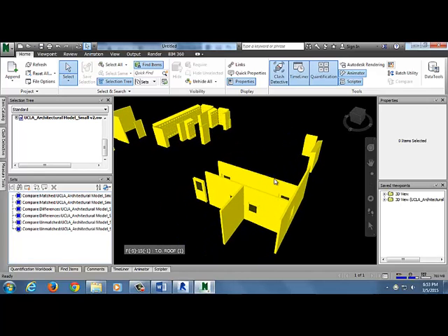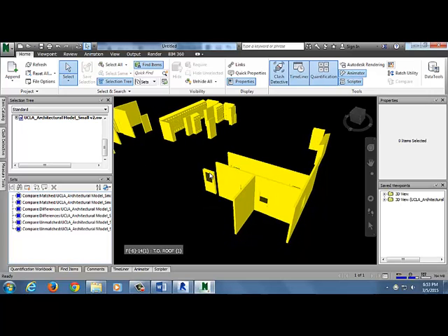Now just because it's in yellow and it's deleted here doesn't mean there's no wall there anymore, right? Sometimes they could have deleted a wall and then added one back in the exact same place with just a slightly different name. So you have to be careful about that. Just because it's yellow or cayenne doesn't mean it's brand new. They could have done a little tricky swap. Does that make sense?